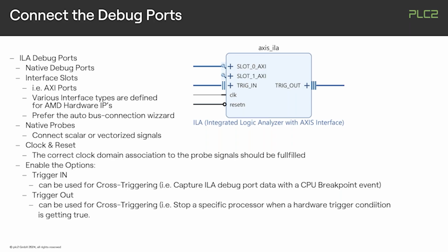Yeah, in the manual way, we have also to make sure that we connect the clock to the proper clock domain, that the reset is also connected to this normally required synchronous reset with a clock domain.